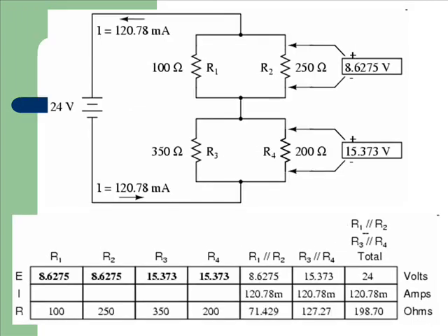Because we know R1//R2 and R3//R4 are parallel resistor equivalents, and we know that voltage drops in parallel circuits are the same, we can transfer the respective voltage drops to the appropriate columns on the table for those individual resistors. In other words, we take another step backwards in our drawing sequence to the original configuration and complete the table accordingly.